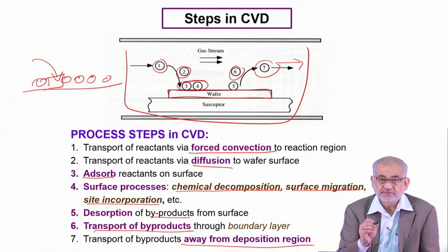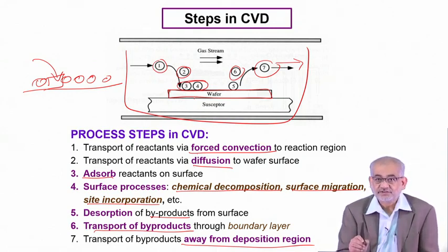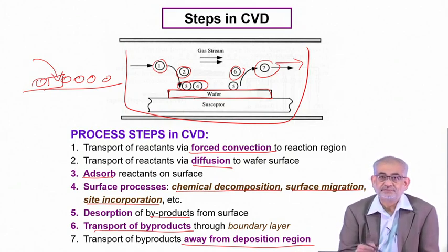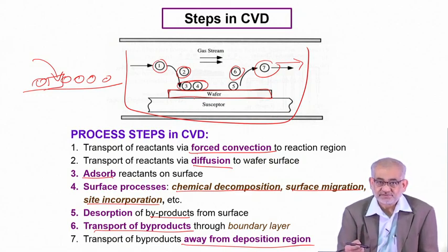In fact, always remember that the coating that we develop here, since it's very thin, there are 2 things very important. One is that the surface topography has to be fairly smooth, not rough. And number 2, the adherence with the substrate should be very strong, so that we don't lose the coating that we develop. And because the composition wise this coating is different than the substrate, fairly different, then the interface is supposed to be fairly sharp, and that can lead to decohesion. So we need good surface integration.